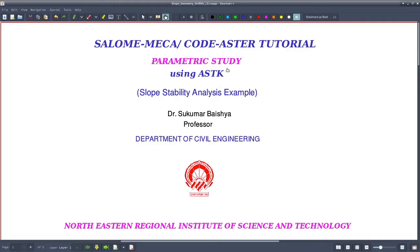Say, for example, in a geotechnical problem, you know that the geotechnical parameters are determined by some laboratory or in situ tests, and there are some inherent errors in the method of determining those parameters. And if the value of a parameter assumed in a design changes afterwards, then how will the system behave? Those kinds of studies are called sensitivity studies. That means how sensitive the result is to the change of some particular parameter. So those kinds of studies are called parametric studies.